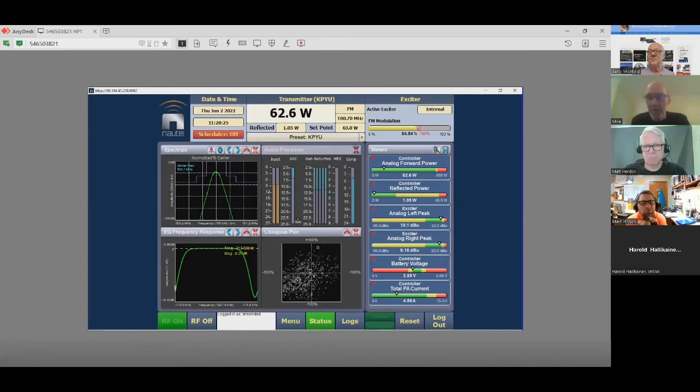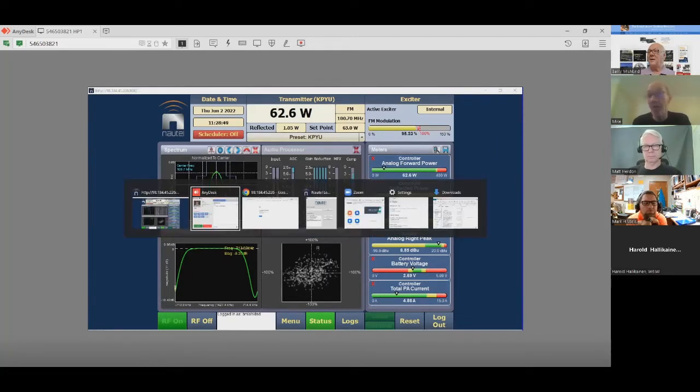So QPSK, and when they get looked at from a signal quality perspective, you want to see, is that really at 45 degrees or 135, or is it 47 degrees? If it deviates too far from what that phase should be, then you can have bit errors that will corrupt the signal. So we show that constellation going through the transmitter.